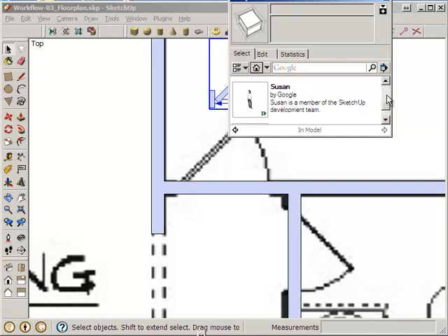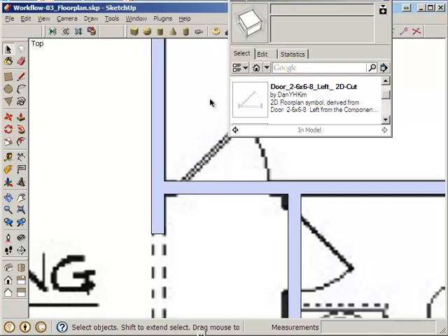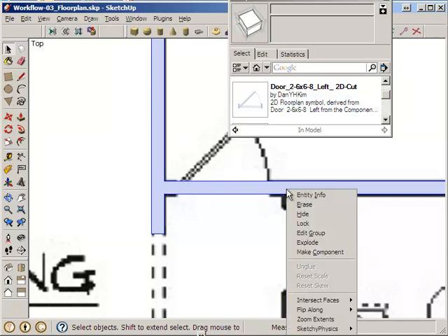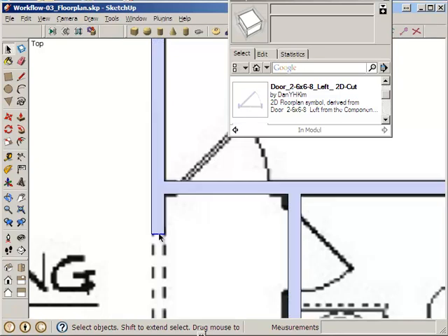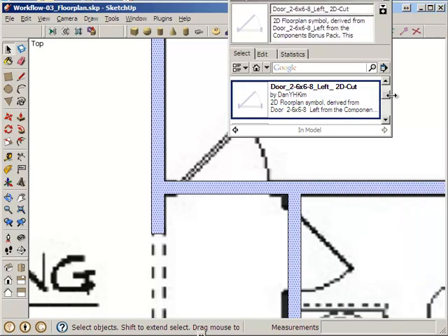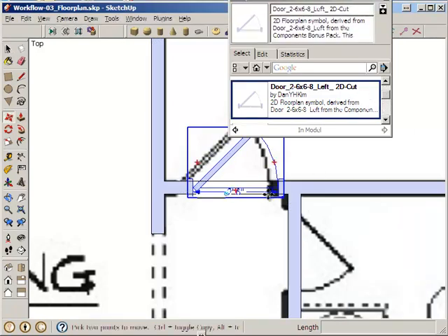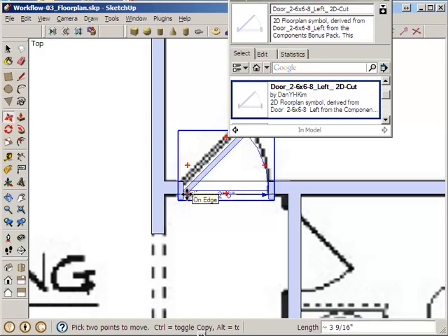And I'll show you how to properly place this into my floor plan layer. So first let's get rid of that one that's distracting. So this is my interior wall group. This is already a grouped object. I'm going to tell it to edit group, and that allows me to have access to the edges and faces of this group. So I have access to this. I'm going to drop this in here. There we go. And as you can see, it's cut itself a hole very conveniently.